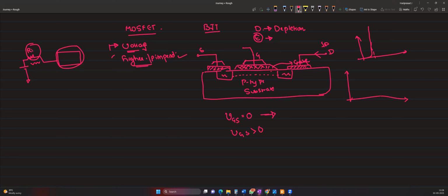As we increase VGS, your ID, against the drain to source voltage, keeps increasing to a certain point and then remains the same. These are various VGS points. For example, VGS here will be 8 volts, here 7, and here 3 volts, and so on. For various VGS, it will increase to a certain point and then stabilize.